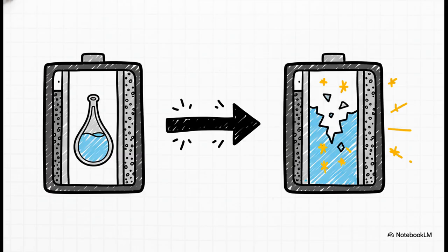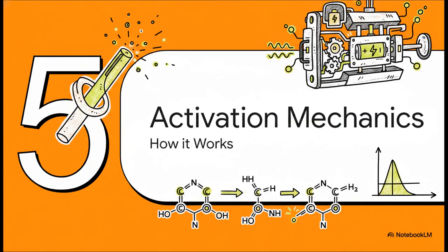In a reserve battery, a key component, which is usually the electrolyte, is physically separated from the rest of the cell until right prior to activation. By totally isolating that electrolyte, these batteries basically eliminate any chance of self-discharge, and they minimize chemical strength loss. Much like primary cells, they are mostly single-use. Some common examples include aluminum and silver zinc batteries. Section 5. Activating reserve batteries, the mechanics.